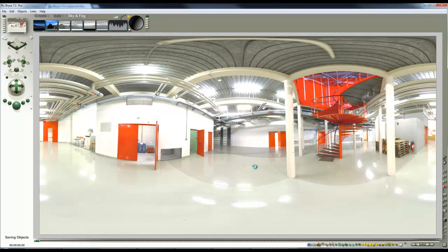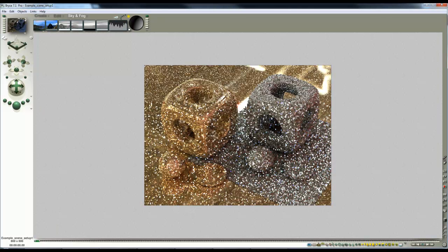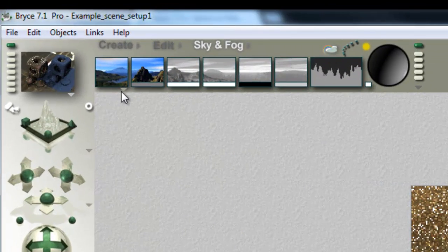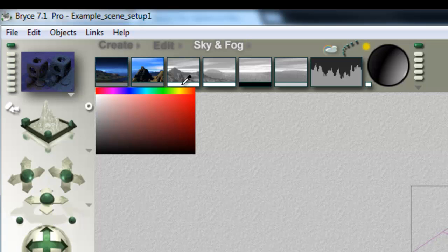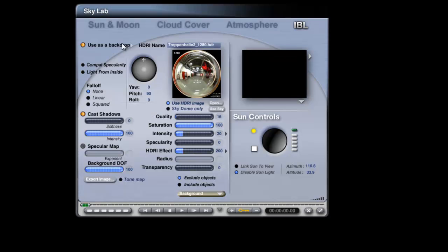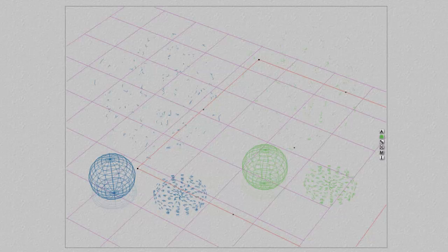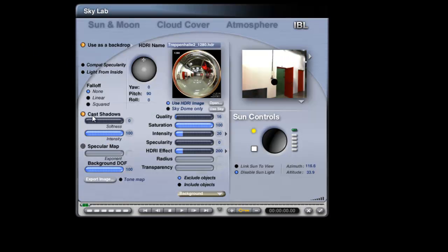So once that's saved, and it'll probably take a little while, we'll go back in here, and what I'm going to do for the time being, I was going to turn the atmosphere off, set the sky to black, go into the IBL tab. I've got add to sky because I was forgetting that also, even if the sun is a visible object in the sky, it will still influence the appearance of the scene. So just by turning the atmosphere off, I've got rid of that. So now things are in a very sort of controlled situation.